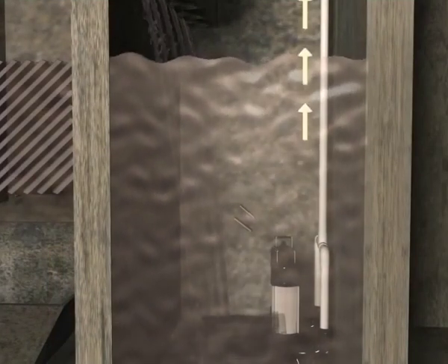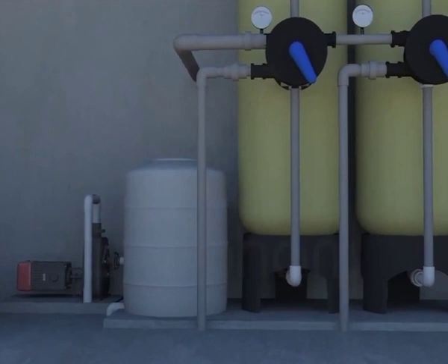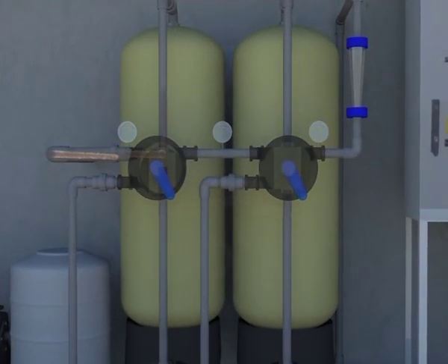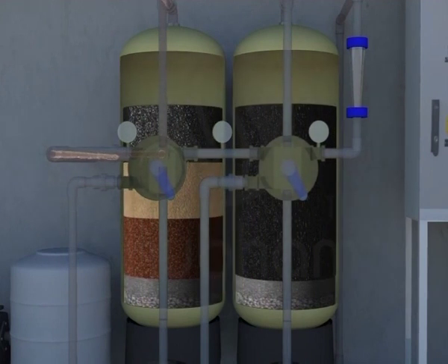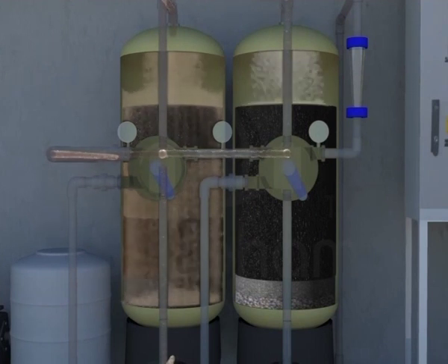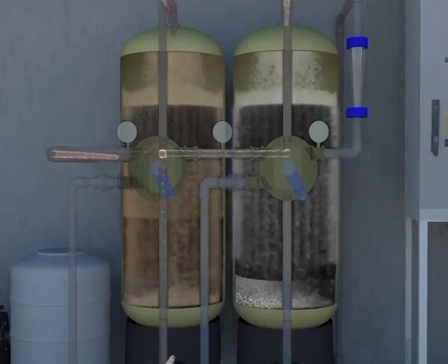After the biological step, treated water can be further polished by means of specific tertiary treatments such as the use of membranes, for example microfiltration, ultrafiltration and reverse osmosis, or other chemical physical processes such as activated carbon, precipitation, chelation for the removal of specific pollutants and to further improve water characteristics. The last process is land disposal of wastewaters. The following methods are used for land application.